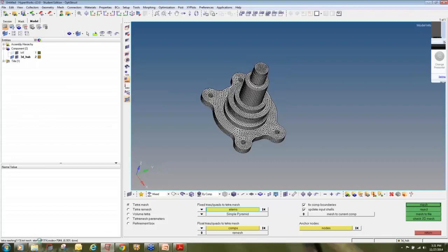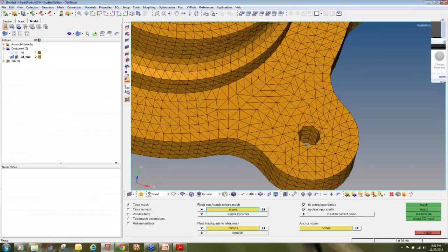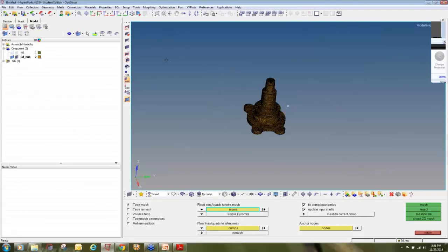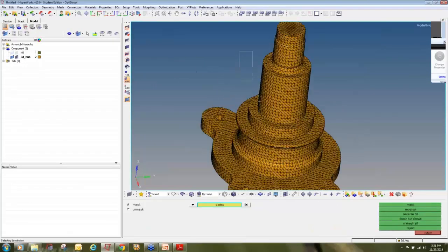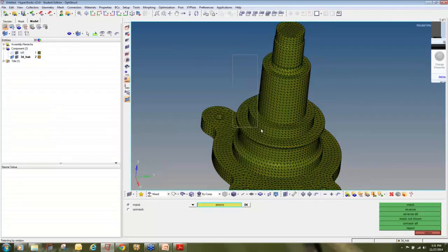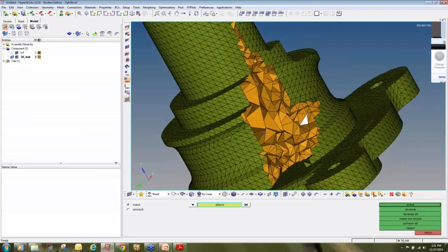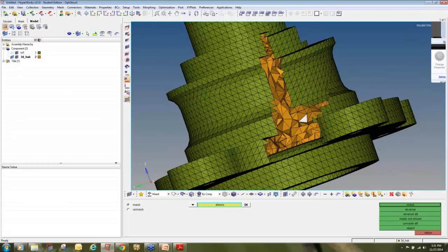Once you click on mesh, at the left side you can see it is processing the meshing and it has created 5932 nodes and generated the mesh. So my 3D meshing is done. So I can go to mask a portion of elements and you can check the 2D and 3D layers. So my meshing is done.